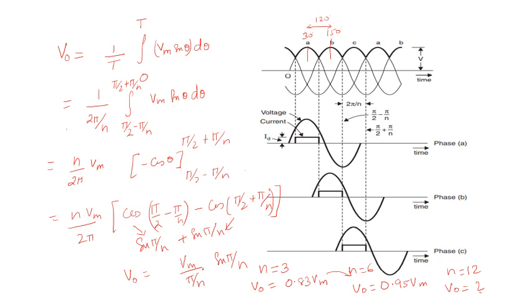Now if you see the current waveform, it is a square shaped waveform. I will tell you the disadvantage of this waveform, because that hampered our transformer. That's why we have changed from 3 pulse to 6 pulse.